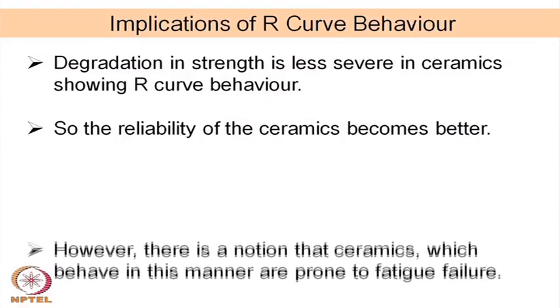However, once the toughening is done by one mechanism or the other, the reliability improves, and therefore, the toughening is also related to the R-curve behavior, and therefore, the materials showing R-curve behavior are supposed to be more reliable than the normal materials.